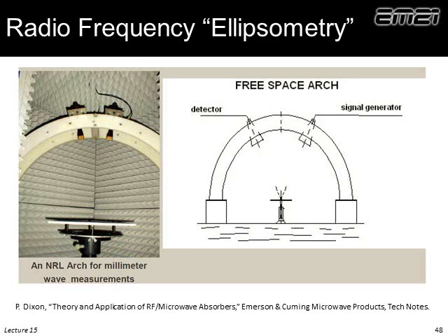So, in fact, ellipsometers are most commonly done at optical frequencies, but here's one that works at radio frequencies. But it is an ellipsometer. And what we see is we have a transmitting and receiving horn. I don't know which is which, but these will change angle. So we can actually sweep angle of incidence. They're probably also sweeping frequency. The sample that we're interrogating is down here. And that's a microwave ellipsometer. And right now, that's probably one of the best ways to measure material properties.